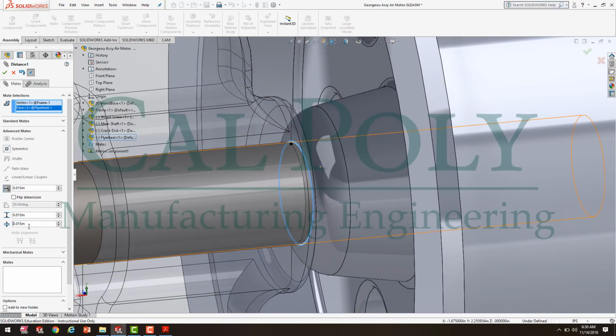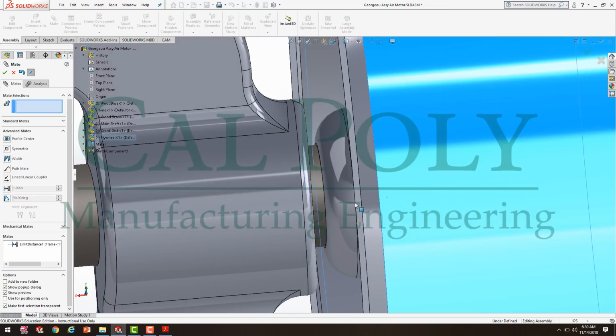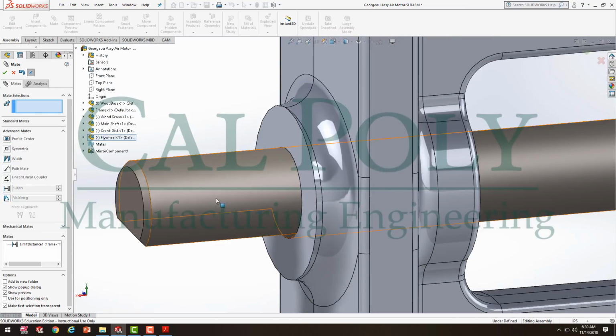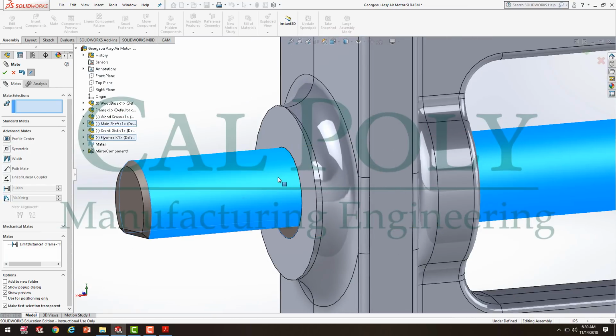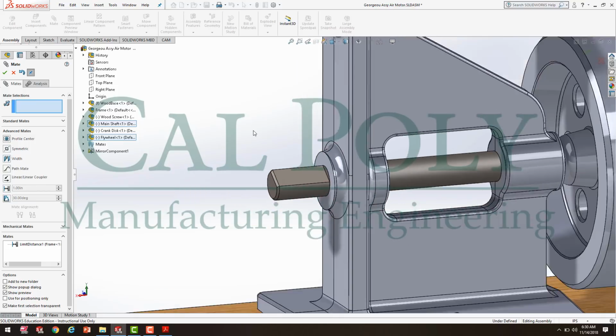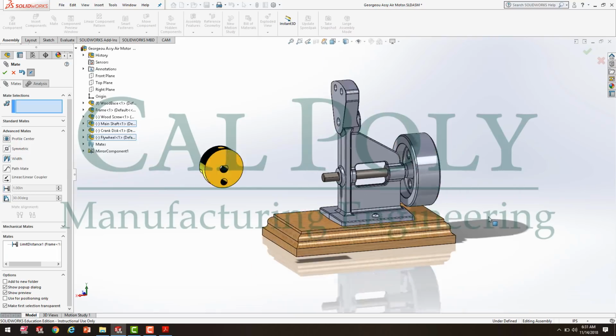And I know the closest would be 0. The farthest away would be 30 thou. When I hit check mark, it sets it at the 15, but it allows it to shift only that distance the shaft would physically move in the model. So it goes those values right there, that it goes from flush to back and forth. So that's how I set the distance and not allow the flywheel to exit out of there.